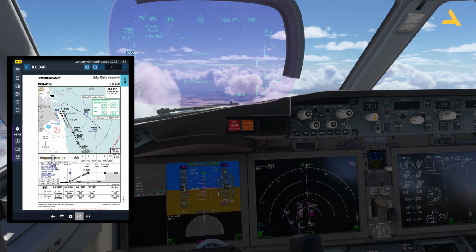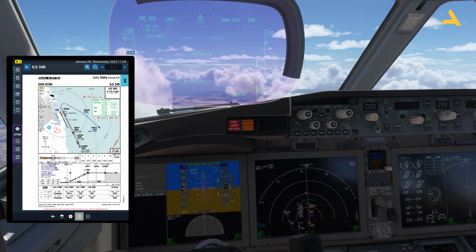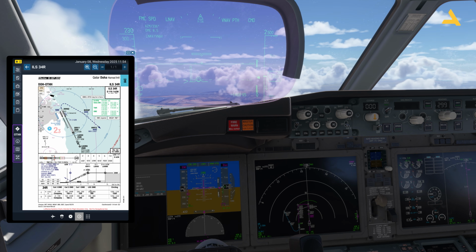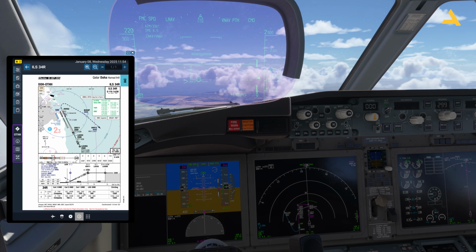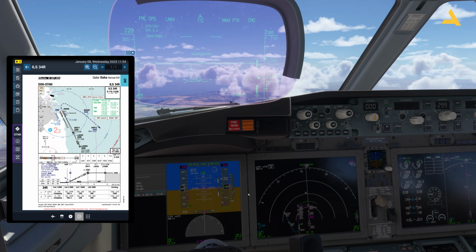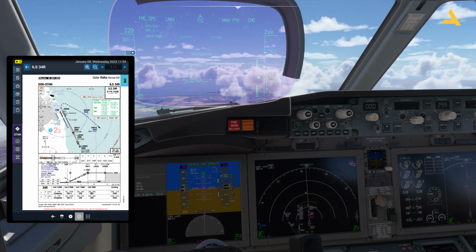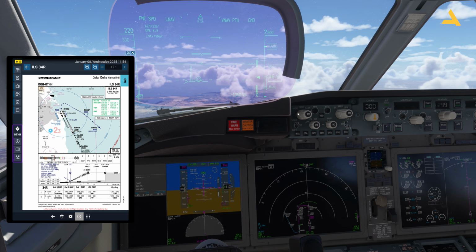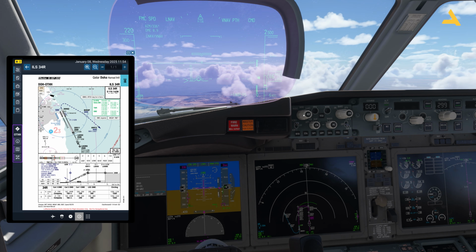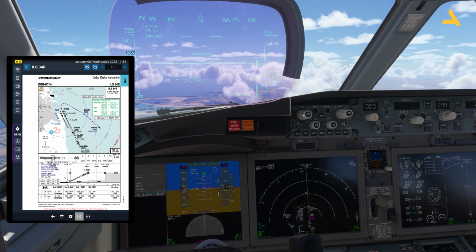So in this type of altitude calculation, radio signals are sent to the ground to get the distance. And the Category 1 and localizer DME, which is distance measuring equipment, DME stands for, is based on the barometric pressure. So you measure the altitude based on the barometric pressure. So for Category 2, I will set it to radio. Just move this knob to radio, and then you can move this smaller knob to adjust the altitude. It will be 150.